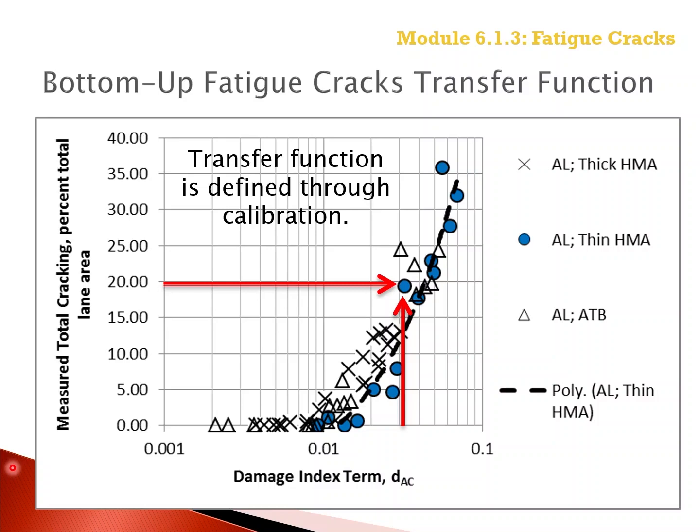For each increment of percent cracking, the calculated bottom-up fatigue damage is related to the percent cracking observed at a specific test section and point in time.